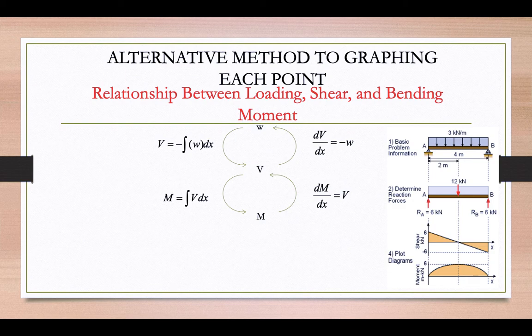In this case, we got a constant, slope 0, so our equation would be y equals 3. And we'd integrate that along with a negative, because the load is pointing downwards, in order to get the shear equation. For the moment equation, we take the integral of this shear equation.